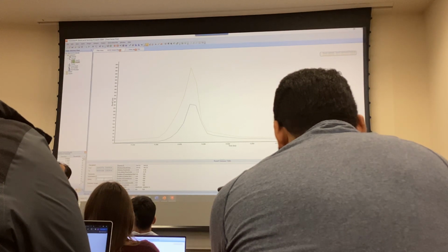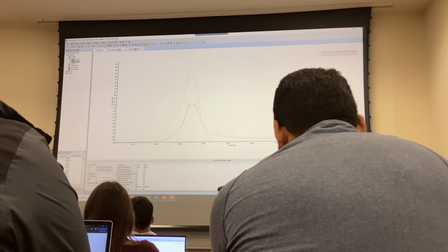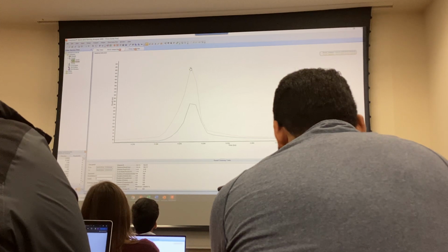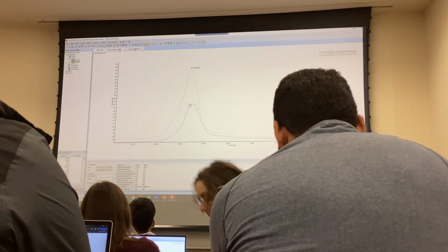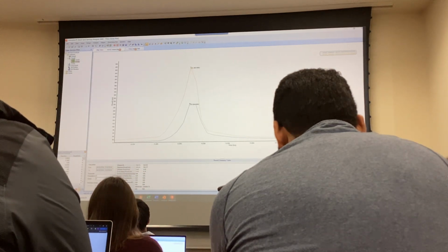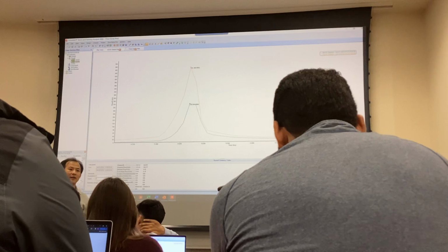So if you ran it at a different time, you can save your pre-development graph, right? And then you can generate the post-development graph just like what we did. Re-import in the pre-development graph. Now, if you do that, I believe that option is going to be open. Okay? So what you do next is you put in the maximum flow that you want to allow the detention basin to release.